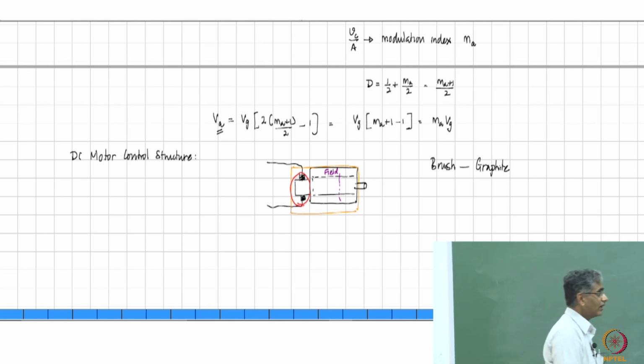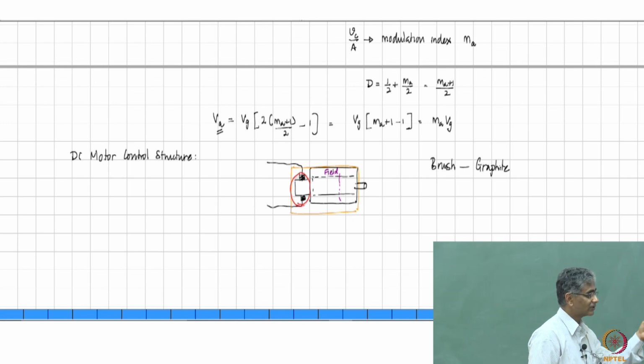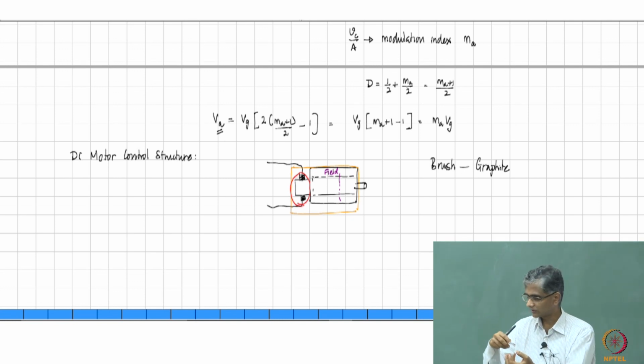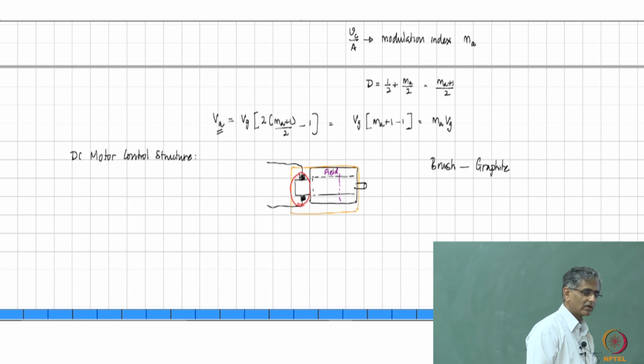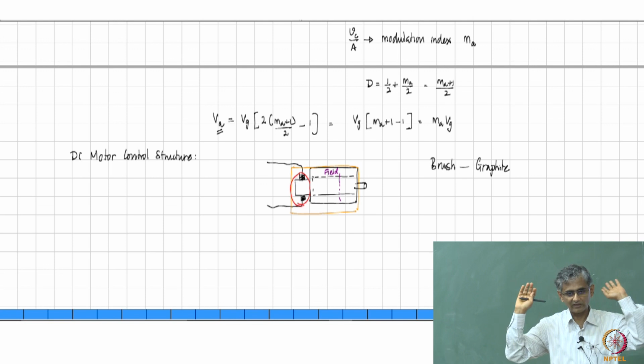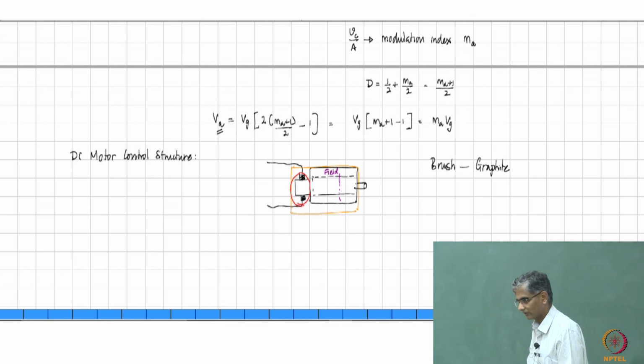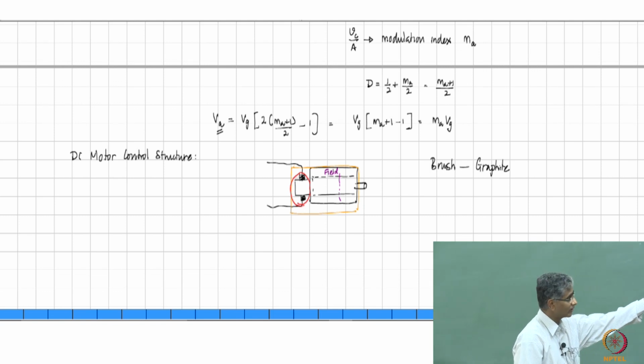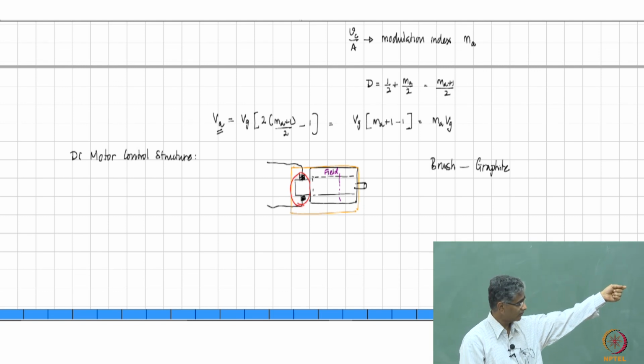It's not only that, the eroded material which is removed from this brush, I mean, it won't just go away into air, right? It has to deposit somewhere. And in which place will it deposit? It will deposit on that cylinder, right? And that is a very dangerous thing. If you allow it to deposit on the cylinder and don't remove it, then it will simply make a dead short between the two brushes.